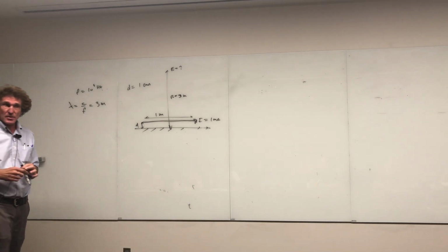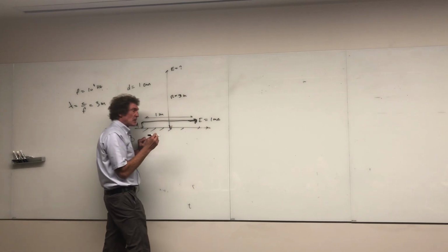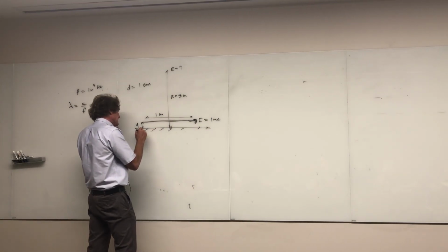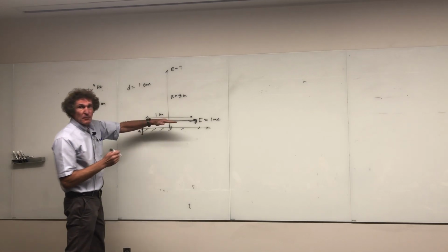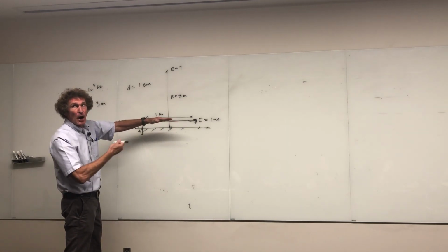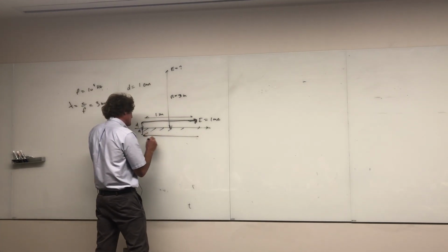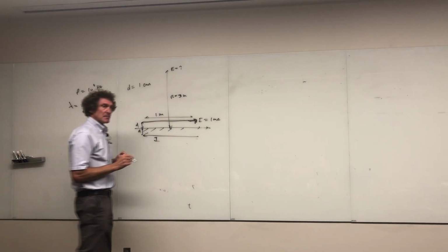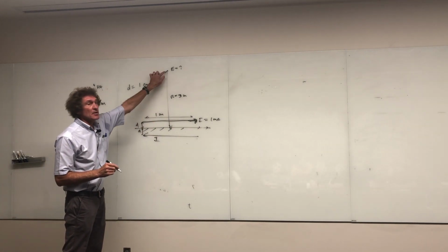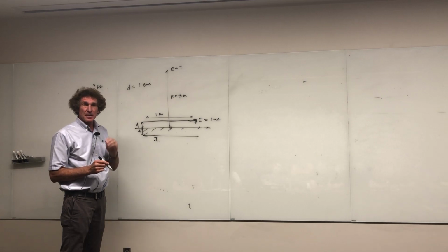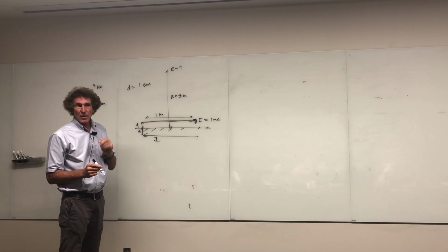It looks like a short dipole antenna, but you'll notice there's a current in this direction here. What happens to the image when we go down a distance d, class? It's parallel to the ground. How does it image? Opposite direction, right? So that means the current down here below it would be in this direction. And that would be the image, correct? Now we need to find the electric field here caused by both of those. Here's where phase becomes critical. And I want you to see this and appreciate why I'm telling you this.